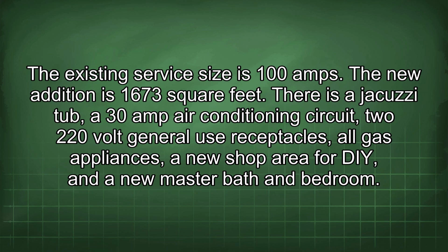The existing service size is 100 amps. The new addition is 1673 square feet. There is a jacuzzi tub, a 30 amp air conditioning circuit, two 220 volt general use receptacles, all gas appliances, a new shop area for DIY, and a new master bath and bedroom.